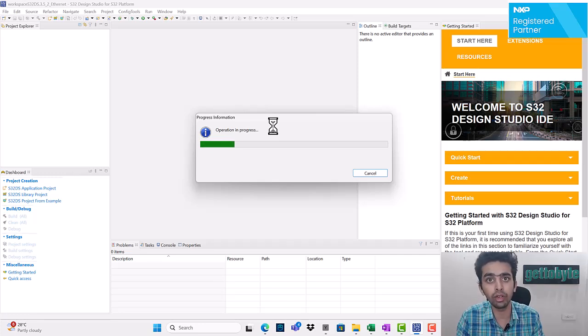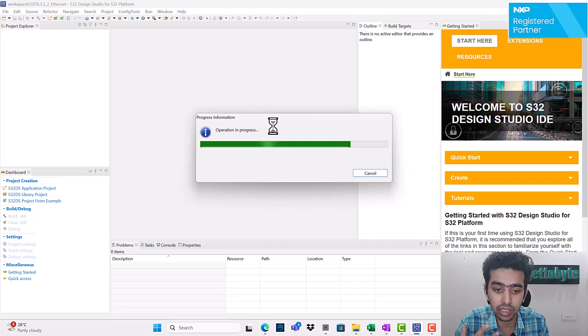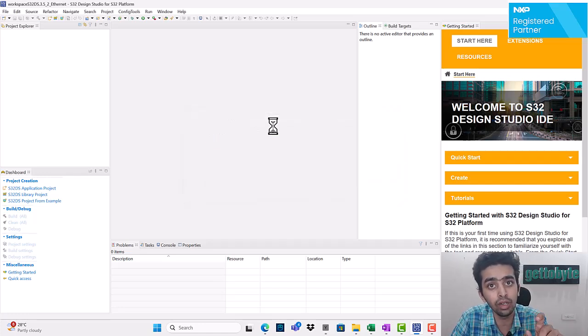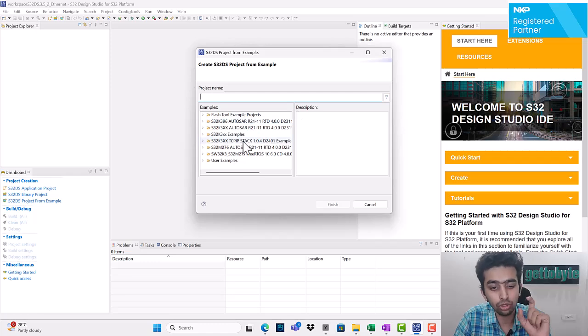On the Arduino environment, we have demo examples for the peripherals and the sensor module. Same way for the software packages that we have downloaded. For those as well, there are demo examples which are provided by NXP. And that is what we are going to see now, and use the LwIP demo example for the K344 MCU, to run the Ethernet and TCP/IP demo.